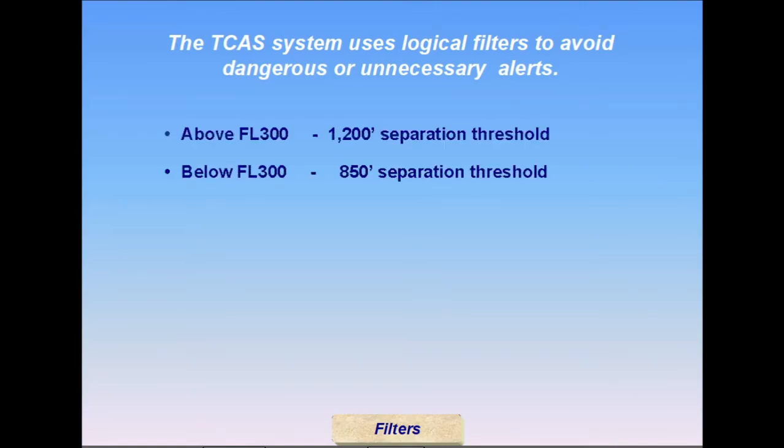Aircraft separated by 2,000 feet above or 1,000 feet below flight level 290 are displayed as proximate traffic within the TA alert area. RAs remain active, however, and failure to decrease vertical rate prior to level off at assigned altitude may cause unnecessary RAs in this situation.